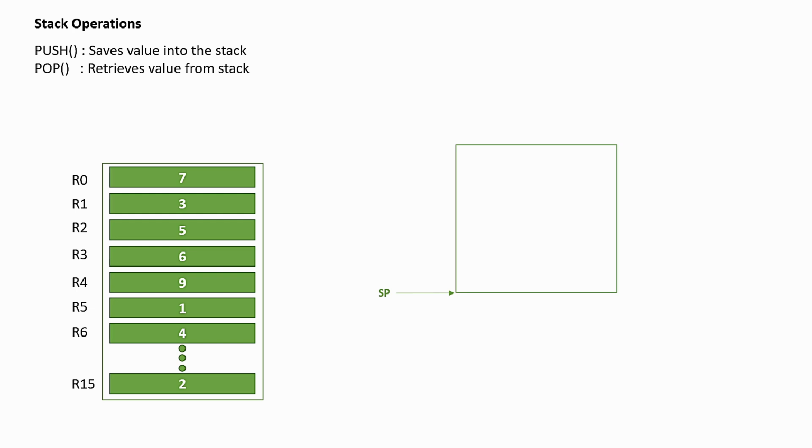And just consider this is the stack, and on the bottom you can see the stack pointer pointing to the top of the stack, or the lowest address of the stack. And as we discussed in the previous video, I am going to consider only 4096 bytes of stack inside the RAM region, starting from 20000000 till 200000FFF. Now I am going to perform push of R2.